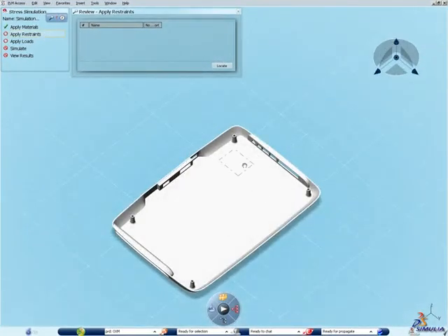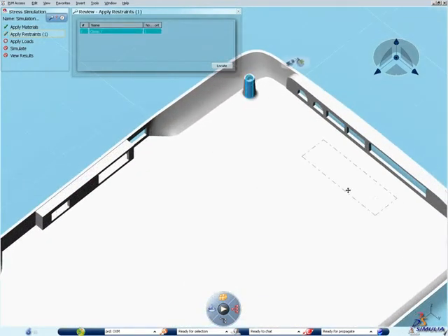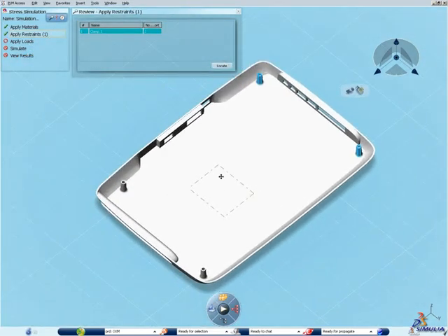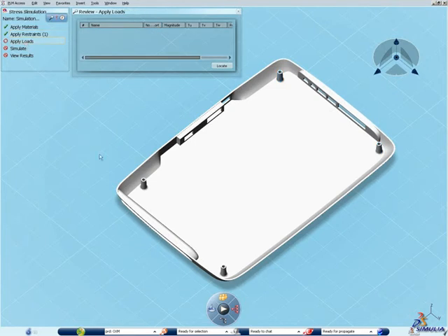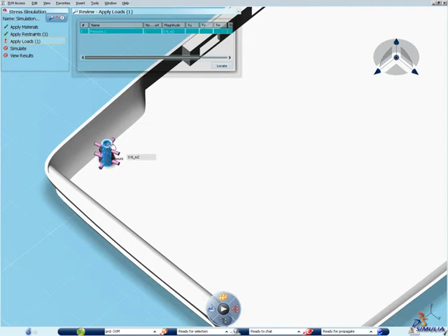We now need to specify how we're holding the part. In our case, if I select these two faces and hold them still, it should be enough to fix this side of the cover. Now, in order for the shape to bend, I obviously need to pull on the opposite side. So let's select the two remaining holes there